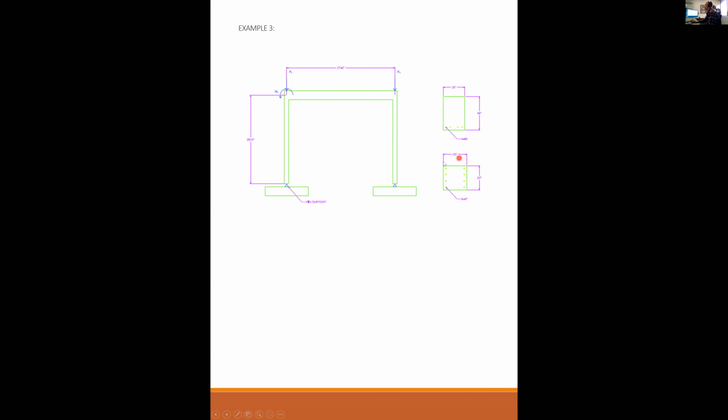So that's why I could do all 8 of them at the same eccentricity. Okay, so I got 8 number 7s times 7.5 inches squared is 270 inches to the fourth.